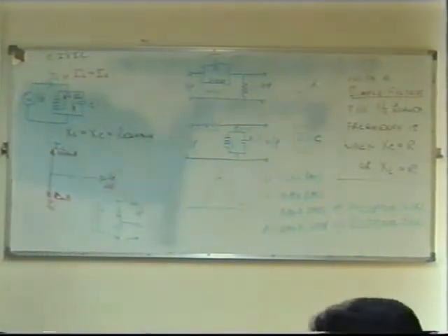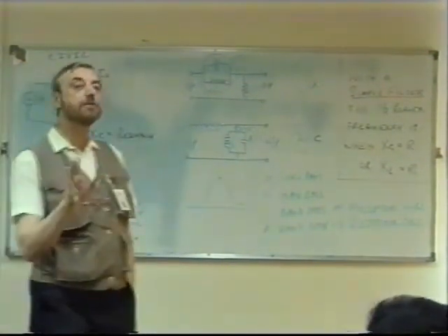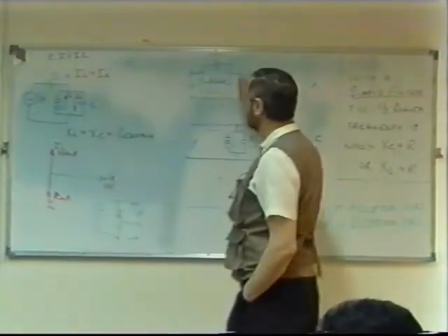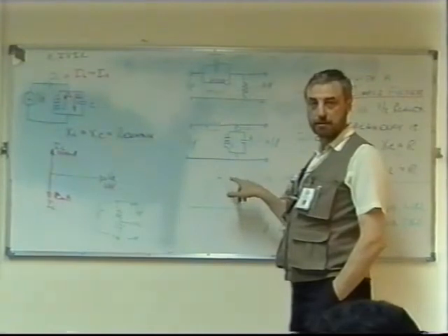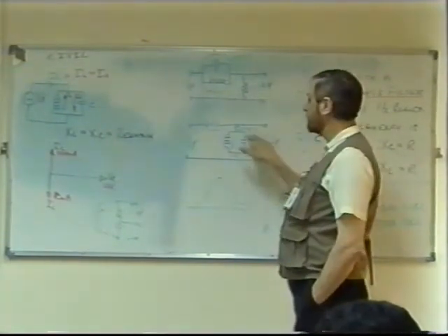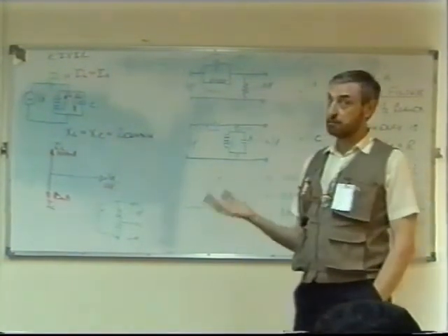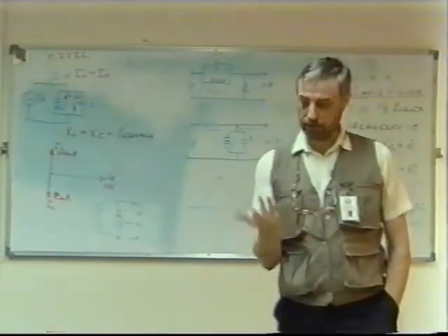It's a series circuit where you get maximum current. They're not as common. That's the reason why in these two examples I chose parallel inductor capacitors. And using those together with the resistors, you can use it either as a bandpass or a band stop, depending on how you connect it.